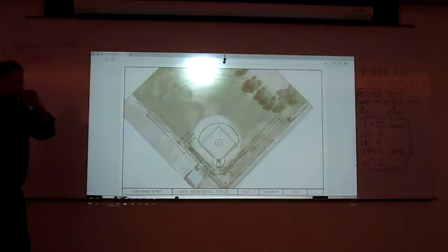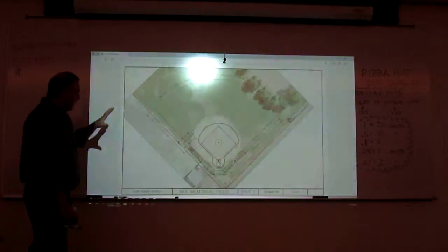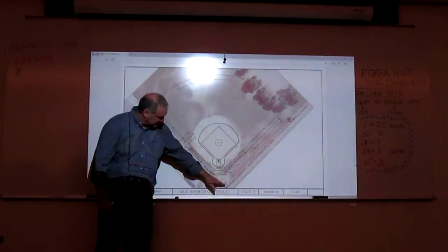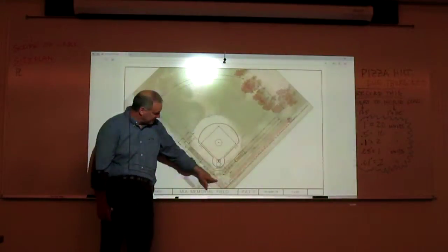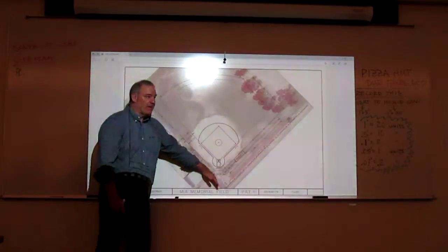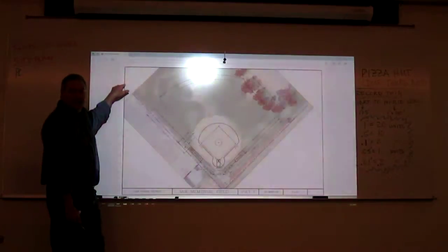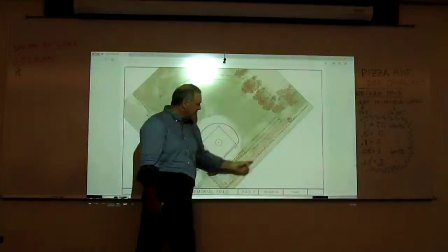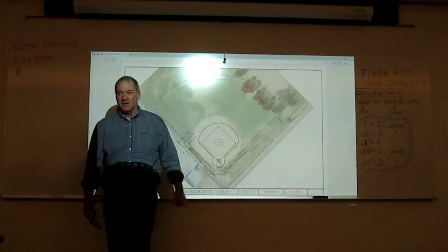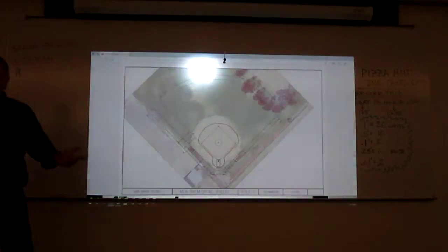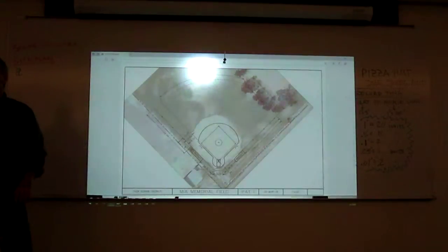Now a couple things that you want to pay attention to when we get out there. When we took these shots down in the corner, we used this little section of fence right in here, as this part of it, and then we used this fence back over here. So we have something we can draw a line through here. We used this fence for this property line. Okay. So we need that. In fact, that property line is really the basis for the entire design.